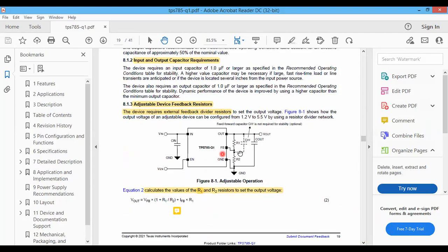Right. So this is the typical application when you make an LDO regulator, for example for your Arduino project or any automotive application. This is a 5-pin device. For enable, you can either connect it to a control circuit, or simply tie it to the input if you don't want to control it and always want it running.